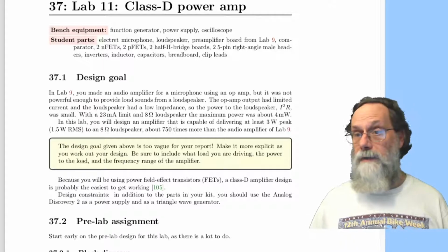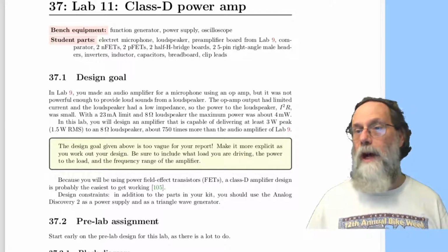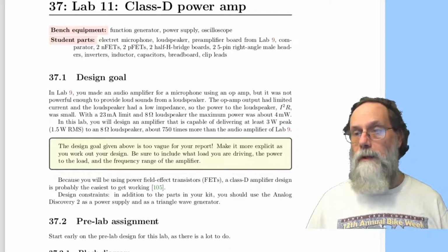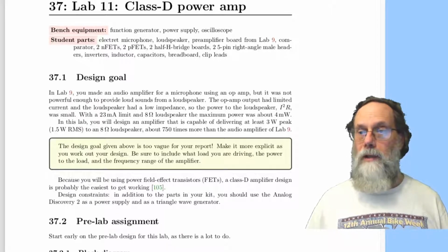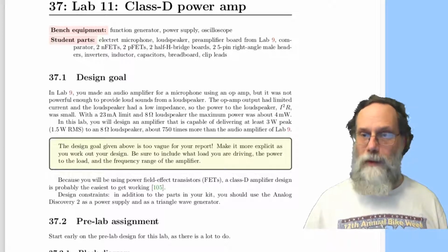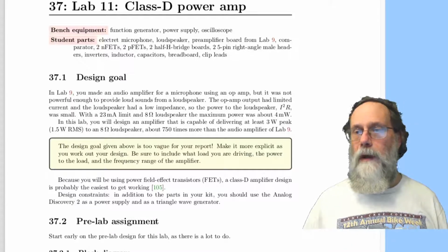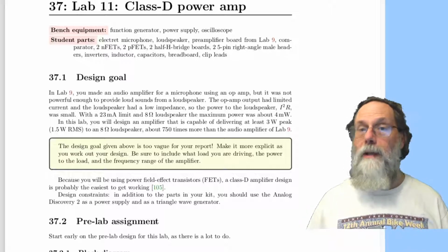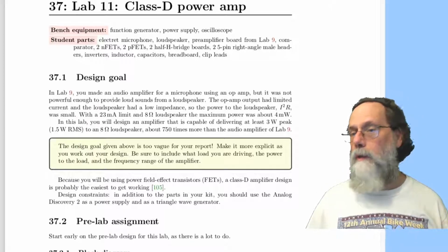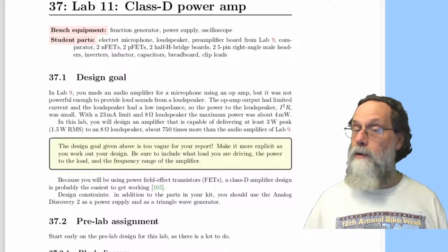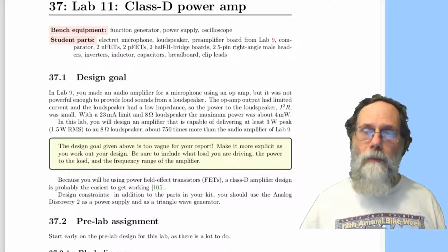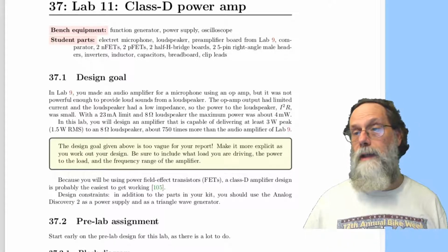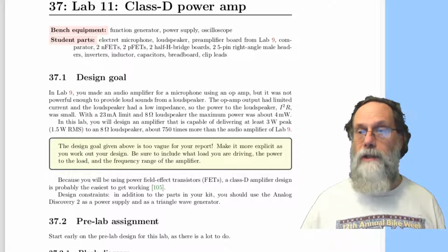Now, the design goal that I've given you there, that you've got to get at least 3 watts peak power into your loudspeaker, is not a sufficient design goal. So one of the things you have to work out in doing the initial design is to figure out in detail what the actual specs are for the amplifier you're going to make. How powerful is it going to be? What frequencies is it going to handle? What sort of load are you driving? Are you driving just an 8 ohm loudspeaker, or is your loudspeaker something different? What are you taking as input to the amplifier? All these things are part of the design process.